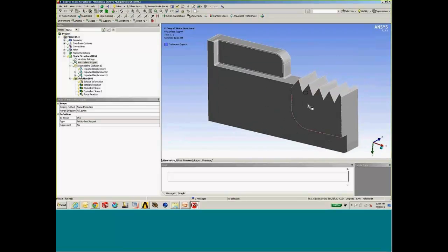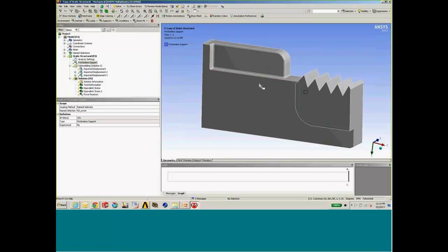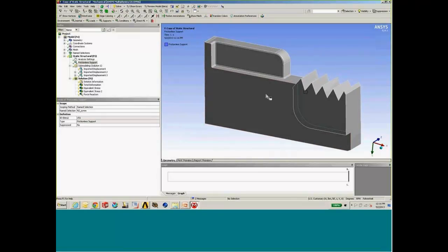If you were using a separate model from the CAD system, you want to make sure that you go through each one of the boundary conditions. You may have pressures applied. You may have, as we saw, temperatures or body forces applied. You want to make sure that anything that existed in the global model also exists in that same location of the submodel.